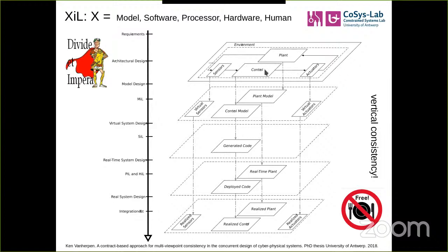and actuators. But maybe we can go to different intermediate steps where either we replace the physical part by a simulation, but we use the real controller, or maybe we stick with a real car, but the controller we simulate on, again, a very expensive and very fast simulation box, using floating point arithmetic, whereas the deployed version will actually work with fixed point.